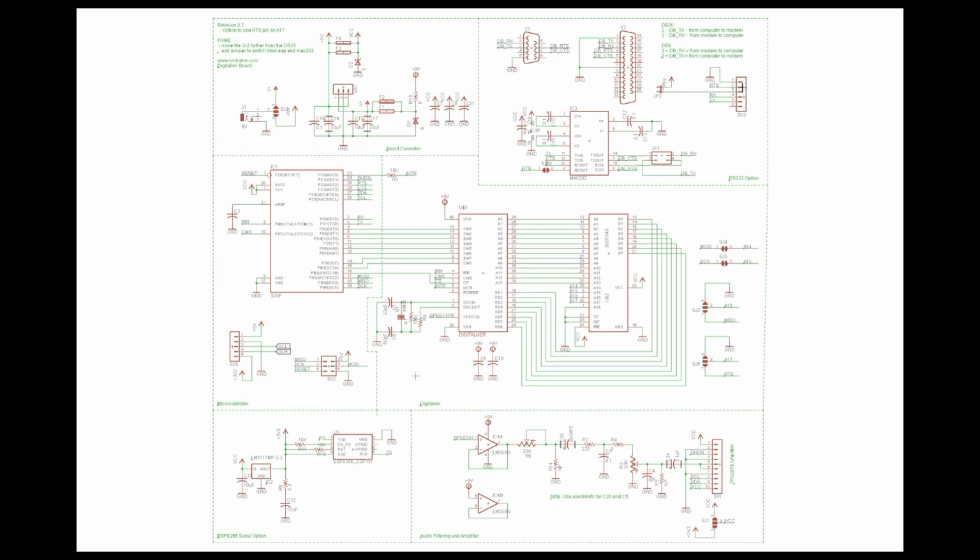Also here is a 6-pin header that fits a popular FTDI breakout cable. So you could use any of the number of widely available FTDI USB to serial cables and plug it in here and be able to plug this into your modern computer that way.